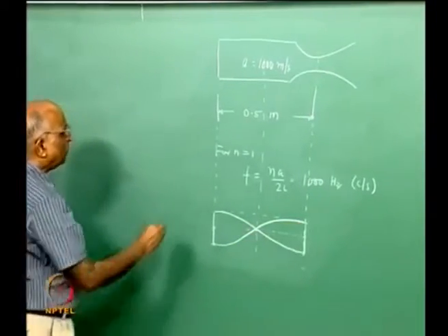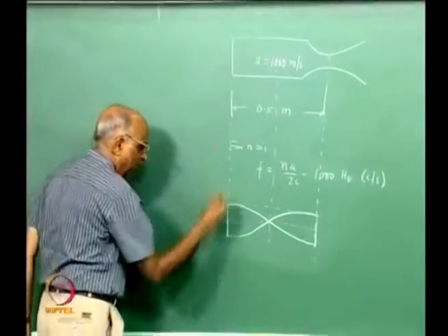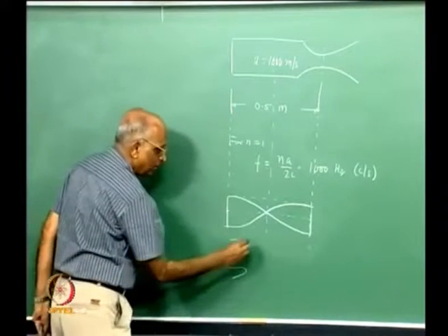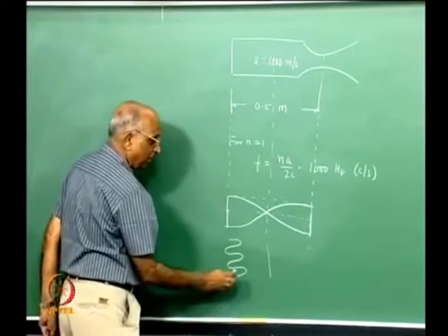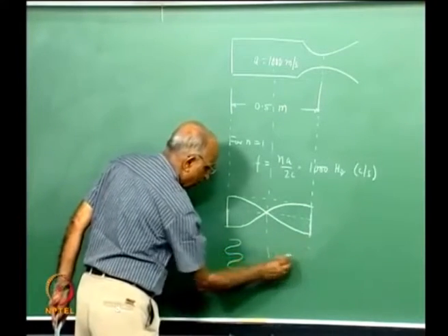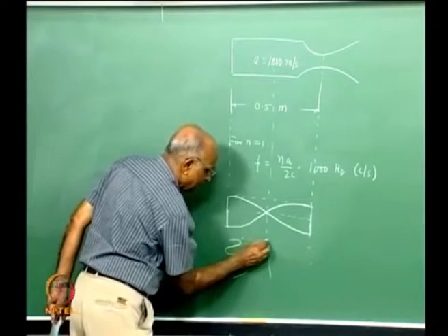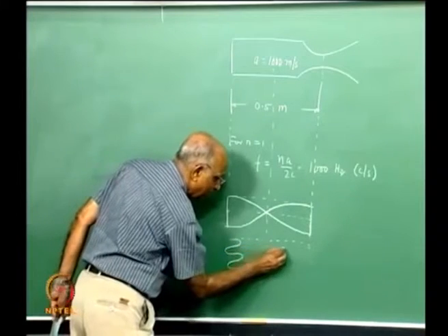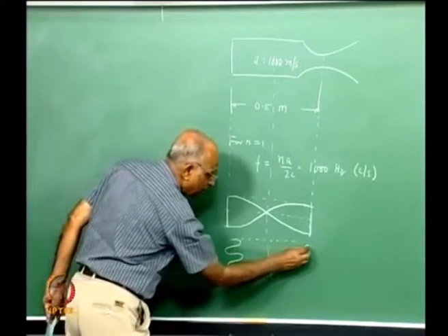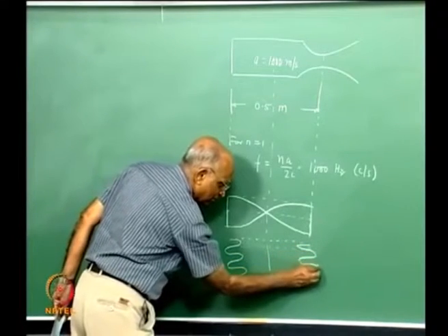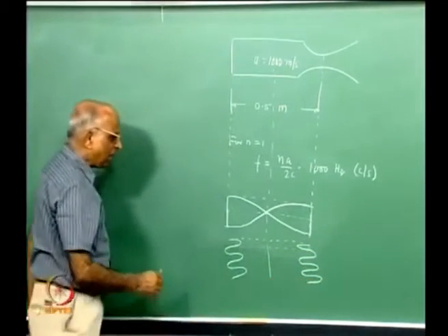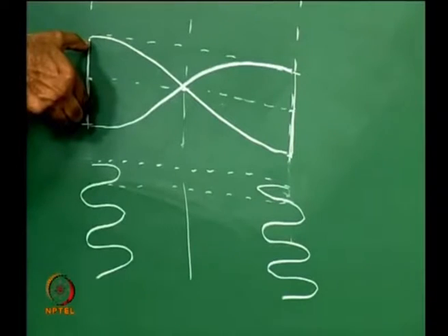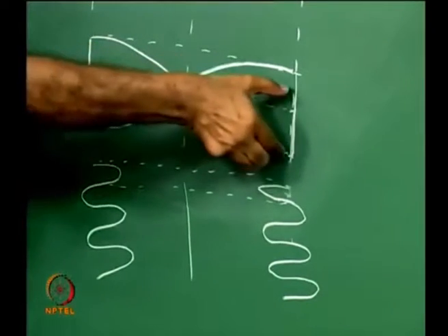In other words, all that I am trying to say is, on the left hand side wherein you have a pressure antinode, the oscillations are like this, of large magnitude. The oscillations here in pressure are 0, being a node, and over here the oscillations will be of exactly the same amplitude, but of a different phase. Now the value, if it is positive here, will be negative there, and therefore the oscillations are like this. Therefore, at the fundamental, you have large oscillations in the amplitude of the pressure at the antinode regions.